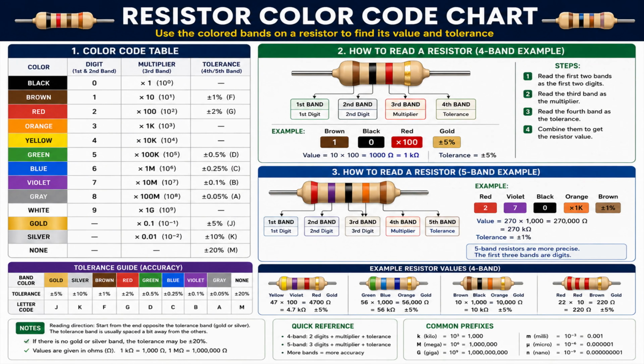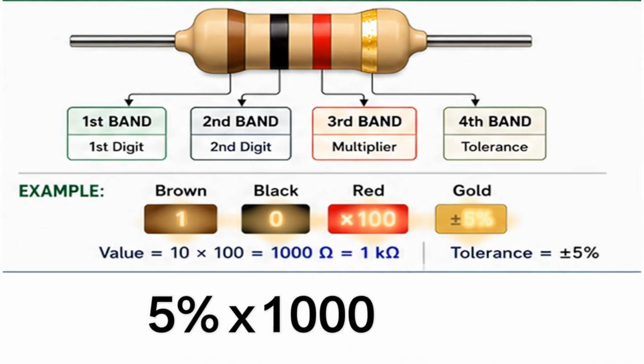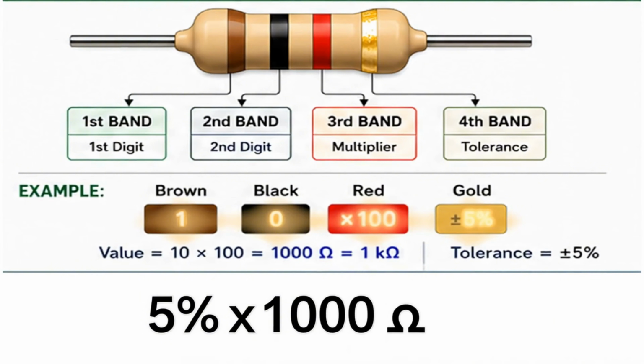And then the tolerance now, and this is something that used to confuse me, because I used to ask why the tolerance is a plus minus. But what it simply means is that resistors have a minimum and maximum level, and it can be anywhere in between. So to find the tolerance here, it's 5% of the 1,000. And 5% is 0.05. So doing 5% of 1,000 gives you 50. So that's going to be 50 ohms.